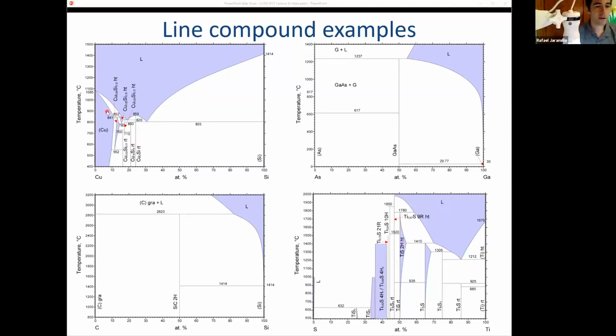I used a silicon bronze when I was in grad school, and we were designing high pressure cells that needed to be actuated at low Kelvin, below 1 Kelvin. And below 1 Kelvin, you can't use lubricant. You can't just use WD-40 because it'll freeze. And so you have to look for metals that slide well against each other. And it turns out there's a whole family of silicon bronzes that various space agencies around the world have developed in the last century.